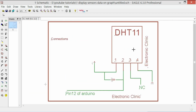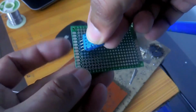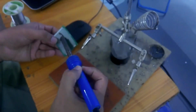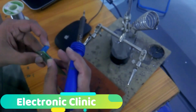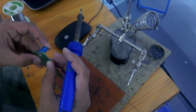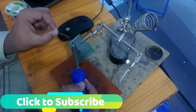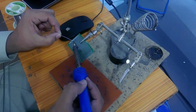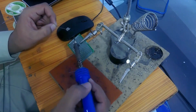Now we will do the soldering. First I solder the DHT11 sensor to the Vero board. Then I solder one leg of the DHT11 sensor to keep it in place. I'm using helping hands for holding the Vero board and then start soldering the remaining legs of the DHT11 sensor. Make sure you don't apply too much heat as it can damage the sensor.